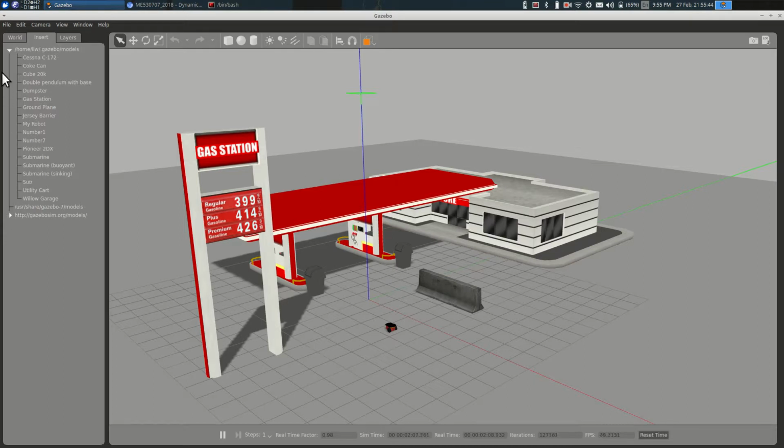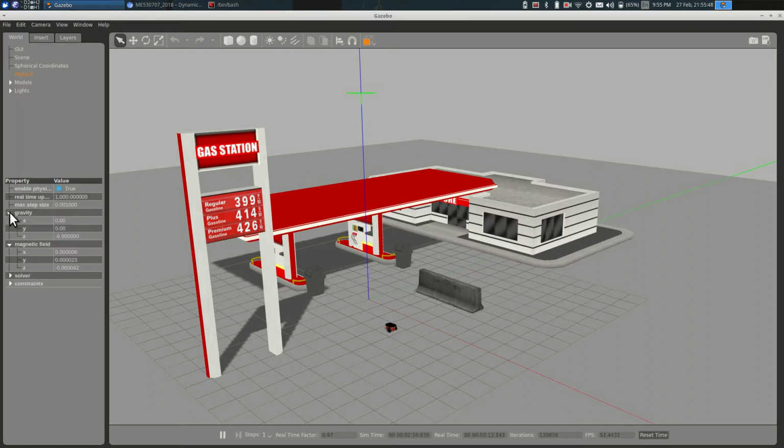And if I am evil and I mess with gravity, which I am, and so gravity here is minus 9.8. Let's make gravity plus 0.1. The things that aren't attached to the ground, like mobile robots, start floating. Now back to minus 9.8. Bonk. And so you see that it dropped down. The buildings didn't fly because they're not mobile and they're fixed in the world, but the mobile robot is not fixed. And when it blammed down on the ground plane, the coefficient of restitution and the impact and the contact model governed its behavior. So we've got a real physics model going.